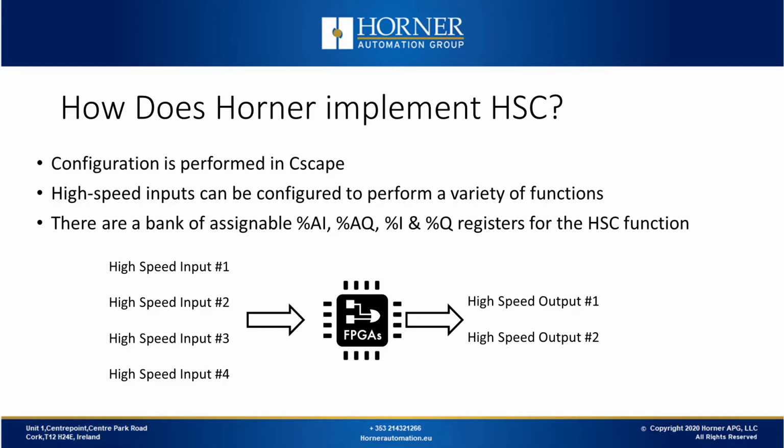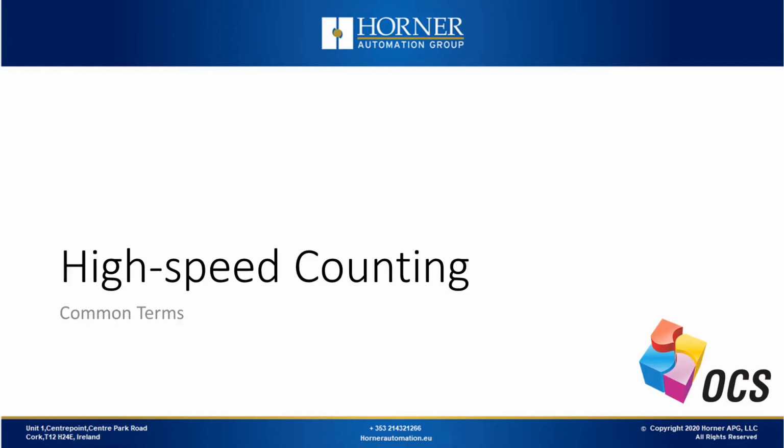Using Cscape, we configure the mode of counting that we're going to be using. Those 4 high-speed inputs can be flexibly reconfigured depending on the application. You have a bank of assignable real-world I/O type registers that you can use for non-time critical functions. This approach of using dedicated silicon means very strong performance with high frequency supported and a lot of flexibility in the functionality of the machine.